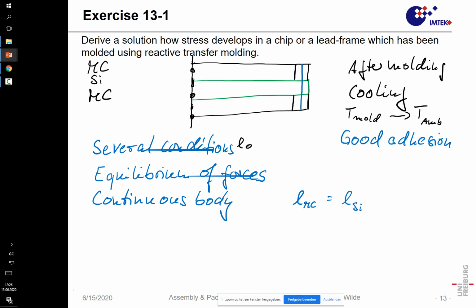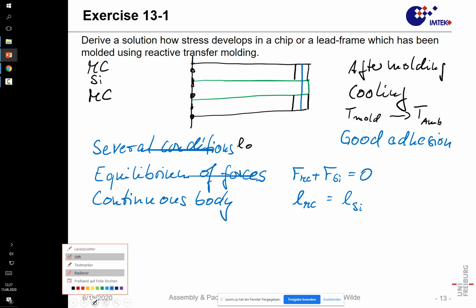And the equilibrium of forces says the forces which pull the molding compound add together with the forces in the silicon to 0. So from the outside it is force free, otherwise it would move, for instance, which it doesn't do. So, yes. What else do we have to know?